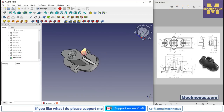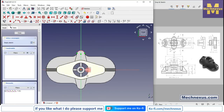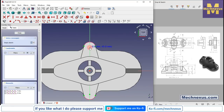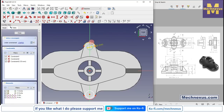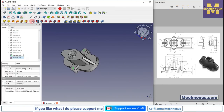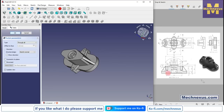and now we will create a hole of diameter 10. So we will select this face and click on the sketch. We will click on the project geometry. We will project this two arcs and select a circle, create two circles, and this is of a diameter 10, so we will select diameter, and this is of 10 mm. We will select this and make it equal. Now click on close, select the sketch, click on extrude cut, and from here say through all, say OK.